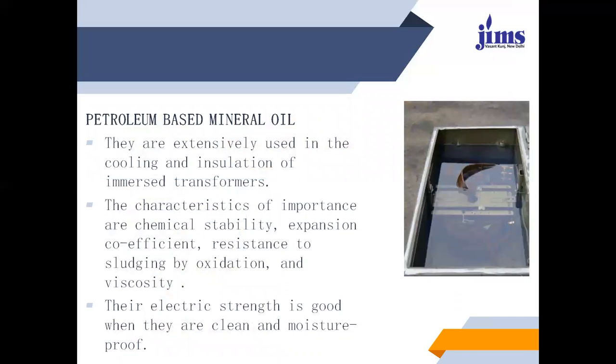Next is petroleum-based mineral oil. It is extensively used in the cooling and insulation of immersed transformers. An immersed transformer means the transformer is placed within the liquid, and that oil provides the insulation and the cooling process of the transformer.